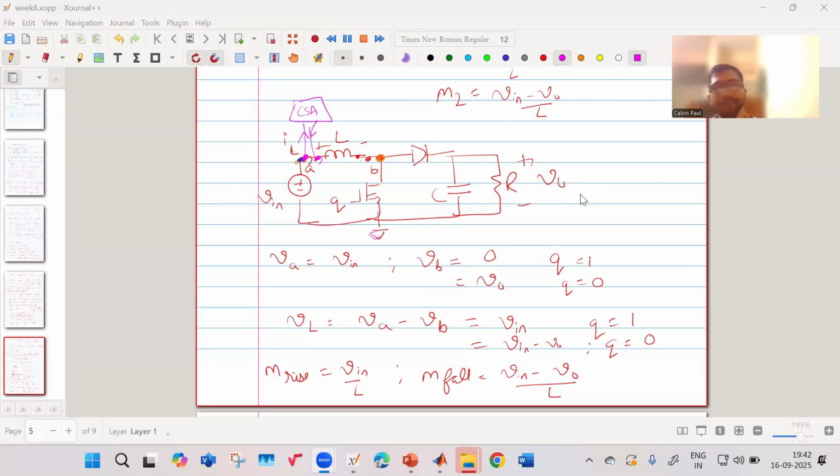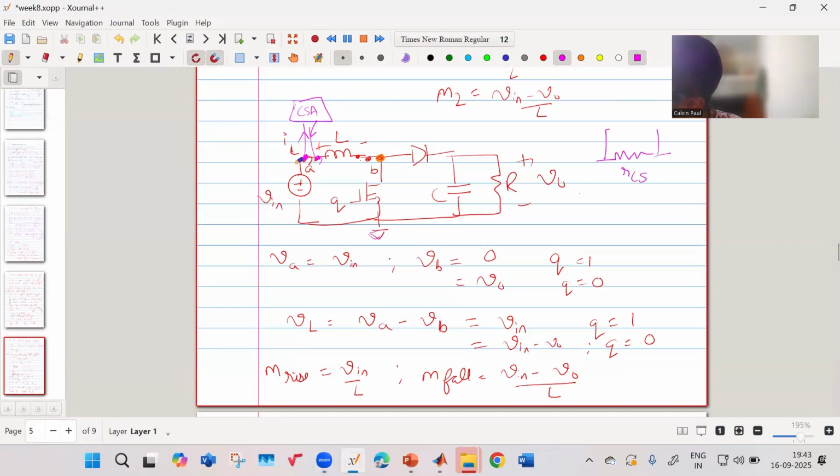Sir, is it connected across a series resistance? Yeah, so there could be a series resistance and then followed by an amplifier, or certain amplifiers have that resistance internal. Either you have a series resistance and then you amplify this, or in certain cases it will go to your current sense amplifier, and the current will go in and come out in this manner.